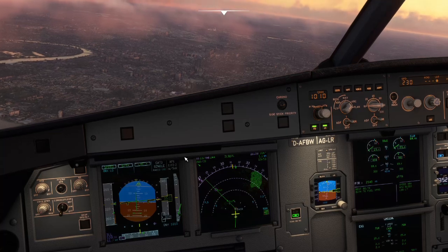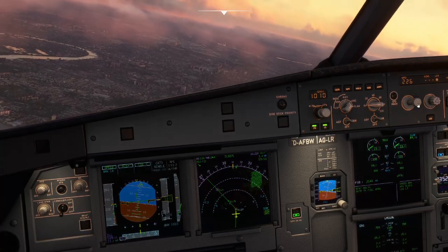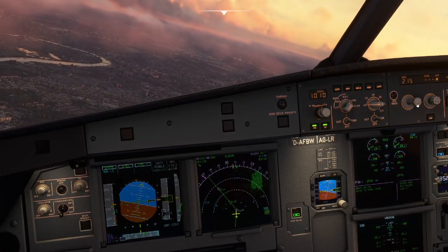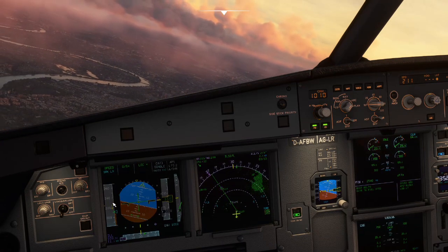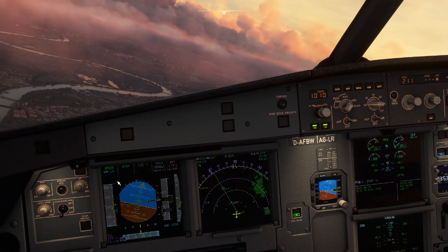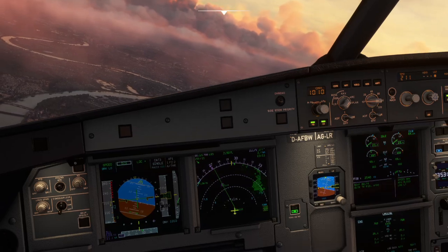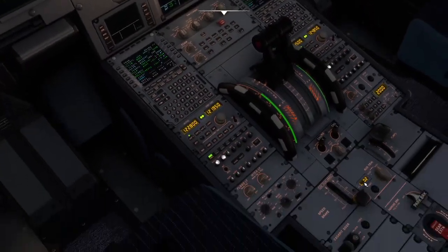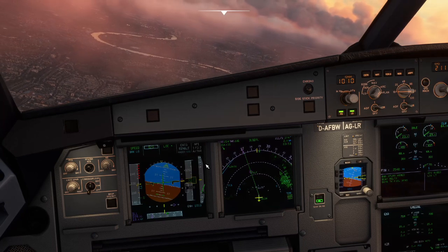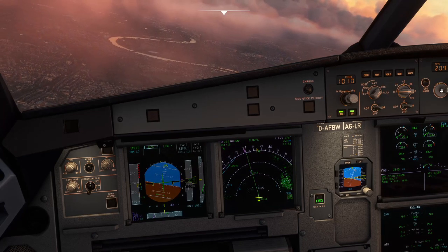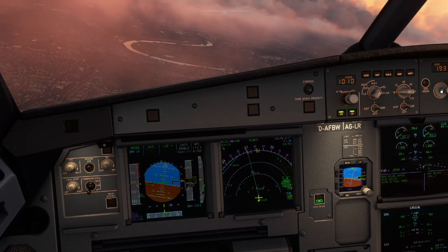It's gone glide slope blocked. Yeah, that approach is ruthless with those constraints. Toggling back to green dot. You can see the flap 1 limit speed there, 230. I'm below that. I've still got the spoilers out. That's acknowledged. We will stow those through to arms. If you end up really stuck, she's gone glide slope blocked.